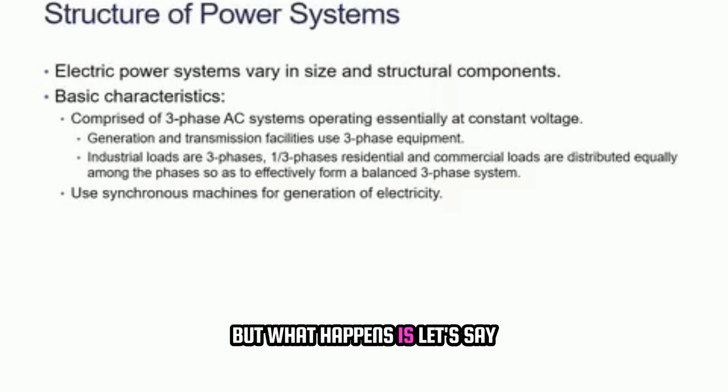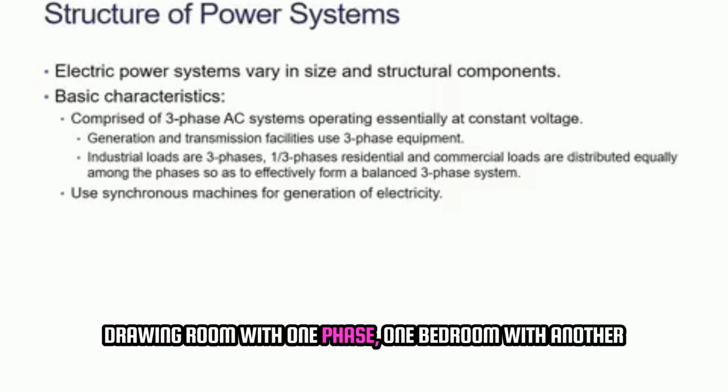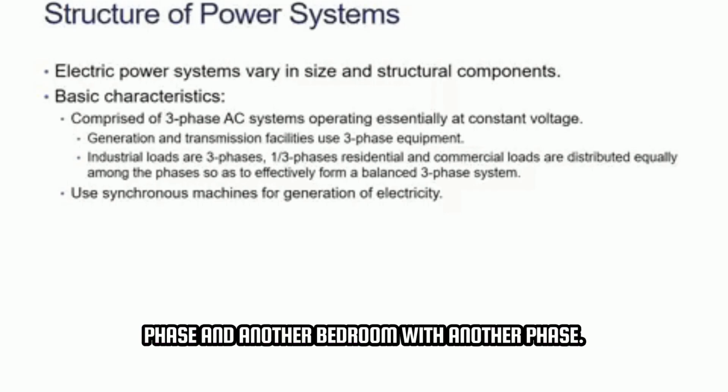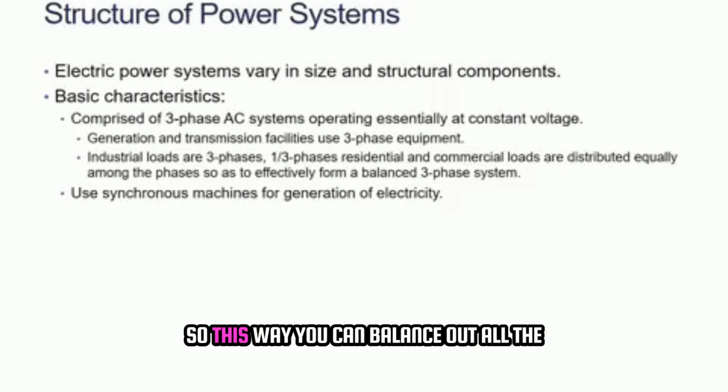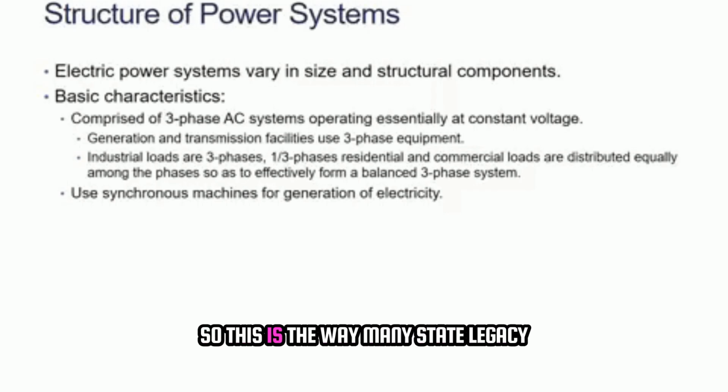But let's say you have three rooms, a drawing room and two bedrooms. You can connect the drawing room to one phase, one bedroom to another phase, and the other bedroom to the third phase. This way you can balance and distribute the three phases. Many state electricity boards offer that feature, and people are also using those three phases.